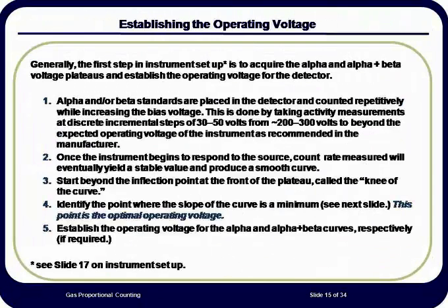Instrument setup is not calibration. Instrument setup establishes where the voltage regions are for counting alpha and beta particles. These regions may be very detector specific. Keep in mind that the detector system must be fully in operation when this function is performed. That includes the proper type and purity of counting gas and the flow rate that will be used to count the samples. The general steps of setup are identified on this slide.